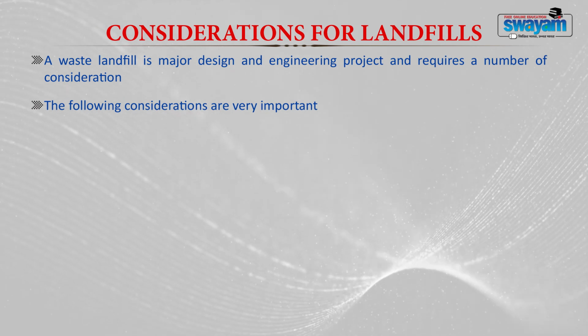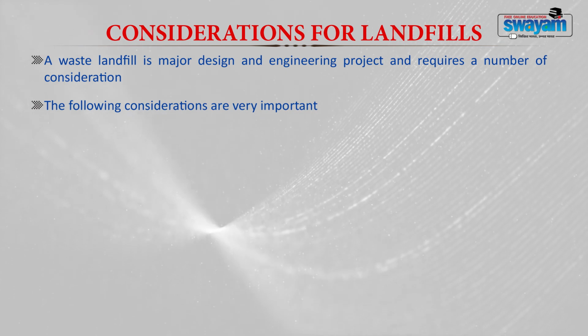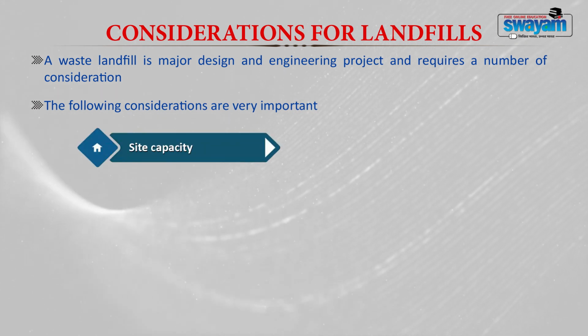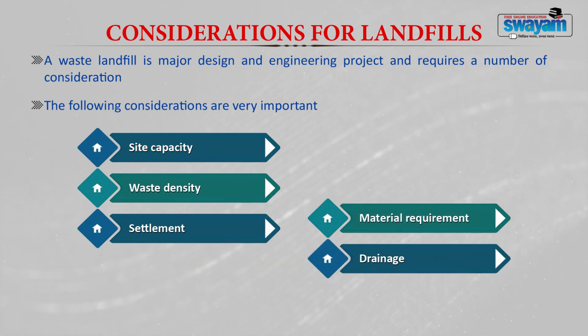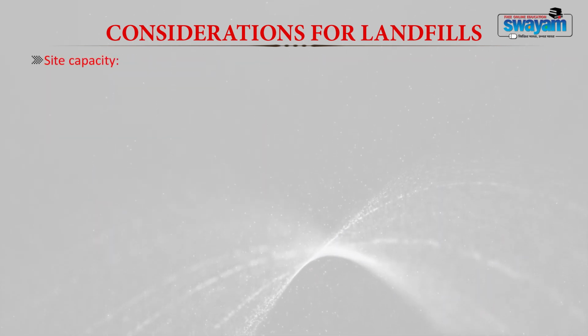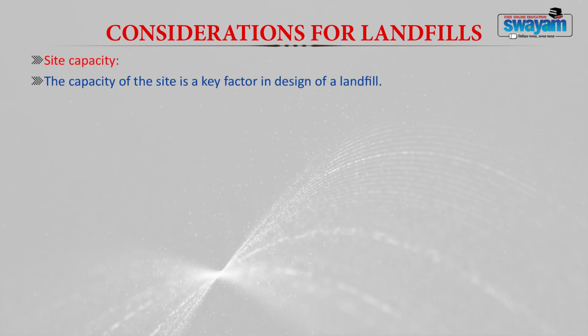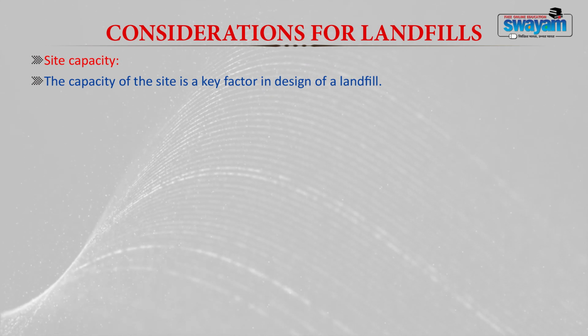Now, the important considerations which you have to look into while engineering a landfill are: 1. Site capacity, 2. Waste density, 3. Settlement, 4. Material requirement, 5. Drainage and 6. Operational practice. Now, we will discuss each of them in detail. Site capacity, as I told you, is one of the important key factors which determines the design of a landfill.